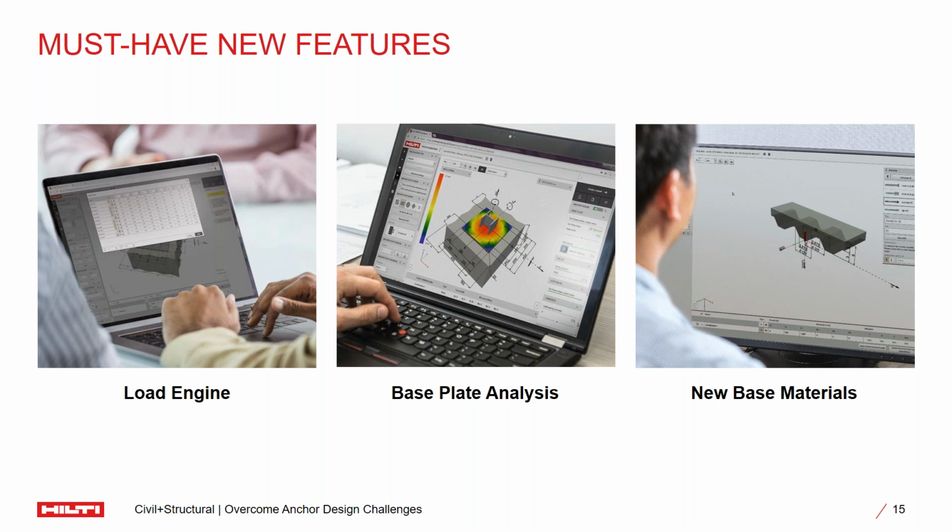I also enjoy the new load engine. Previously, you had to actually compute your factored design forces and then input them into the software for each load combination. With this new version, you can update or import your unfactored loads, select the appropriate load combinations, and then the software will check the anchor group for all the various load combinations that you selected.